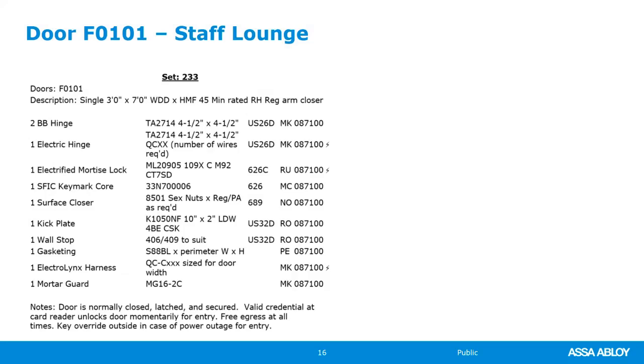Very good question. It's always a debate one way or the other. And sometimes you will find a facility the owner will want one. But if I'm the consultant and I'm making a recommendation, I'm going to recommend they use an electrified mortise lock rather than an electric strike, or if this were an exit device, electrified trim on the exit device instead of an electric strike in new construction. Retrofit is a different story.